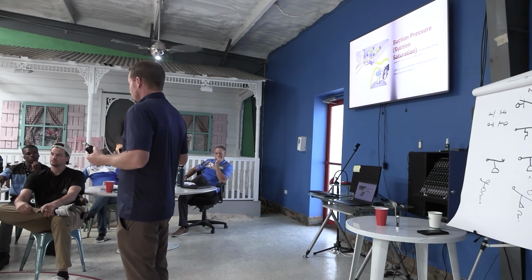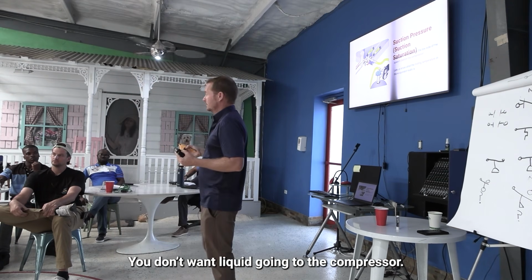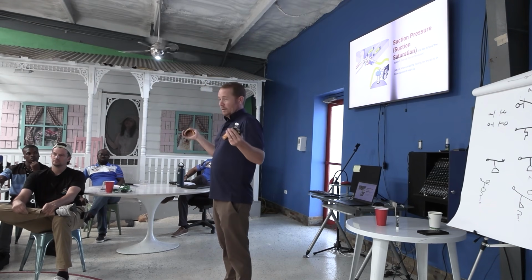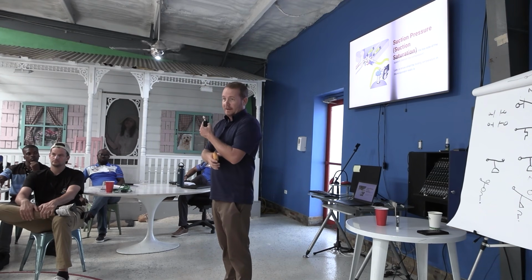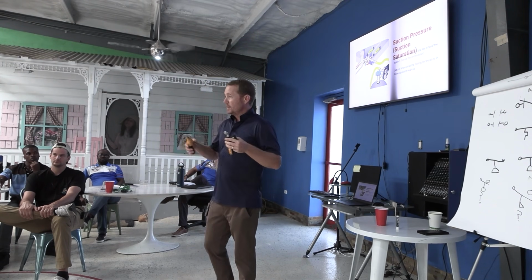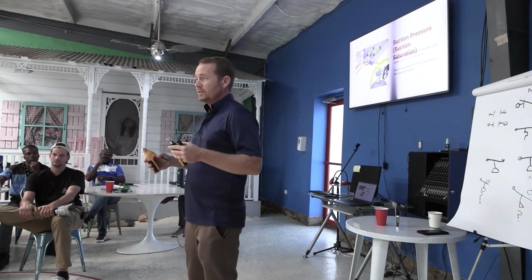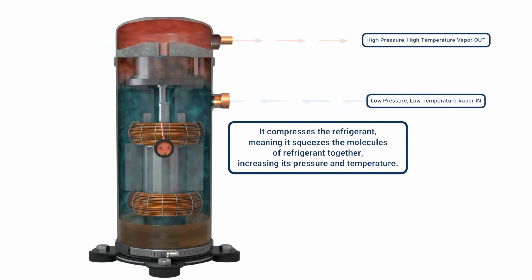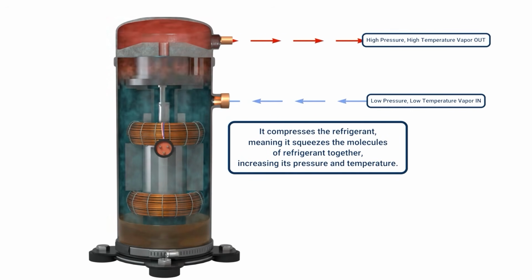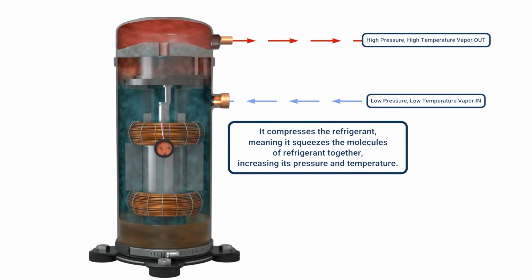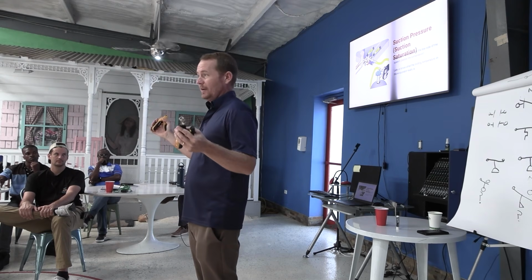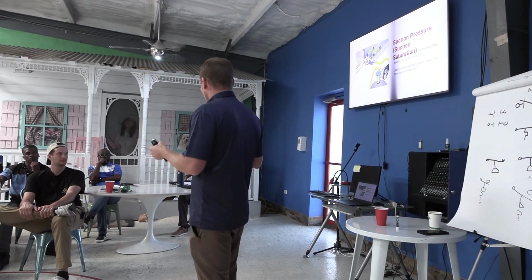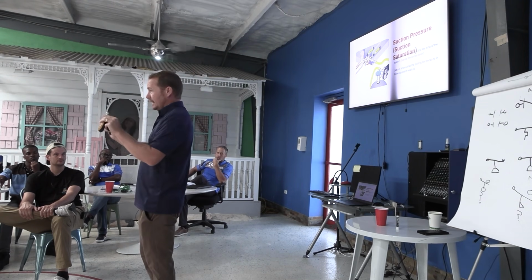No. Why isn't that a good thing? You don't want liquid going in the compressor. We call that flood back, right? So liquid's going back to the compressor. The compressor does not pump liquid. The compressor is a compressor. It compresses vapor. It does not pump liquid. It's not designed for that, right? So if you put liquid into a compressor, parts start coming off, and that's not good. So understanding that is really important.